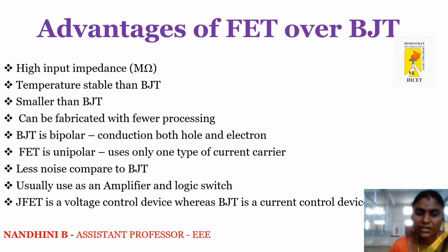Next, when compared with BJT, FET has less noise. Usually, the FET is used as a switching device and also as an amplifier. JFET is a voltage controlled device, whereas BJT is a current controlled device. The advantage of a voltage controlled device is that the losses will be very minimum when compared with a current controlled device.